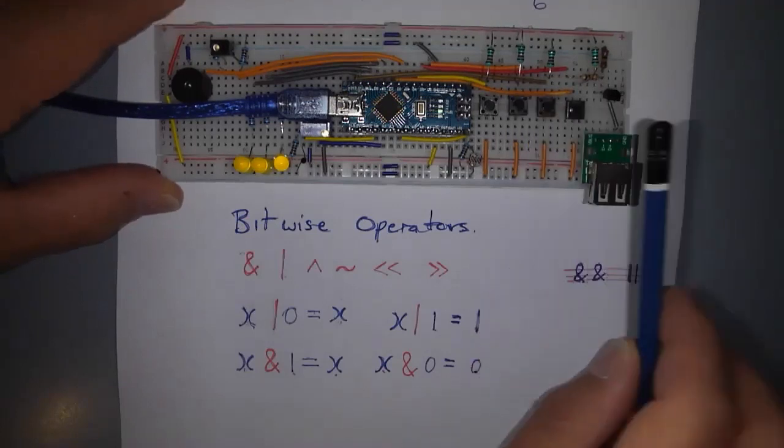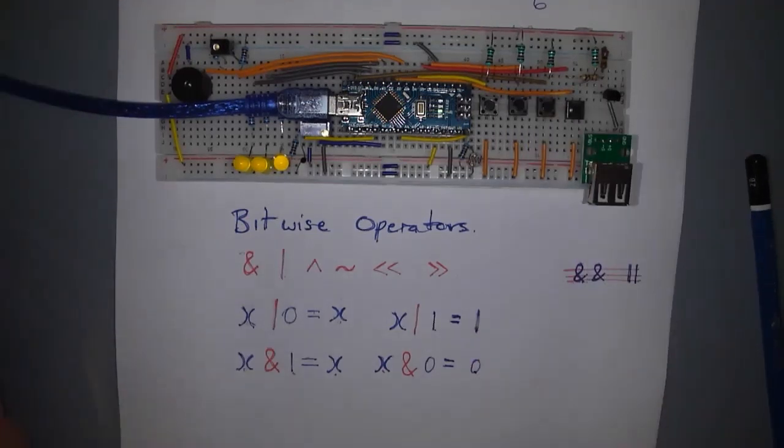Okay, and that's what's happening in this line of code. Here I'm turning off the LEDs and turning them back on again, so my LEDs are actually flashing on and off. But they're flashing so fast that we can't see it. They just appear dim because they're turned off for one instruction period, which on a microcontroller running at 16 megahertz is not very long.